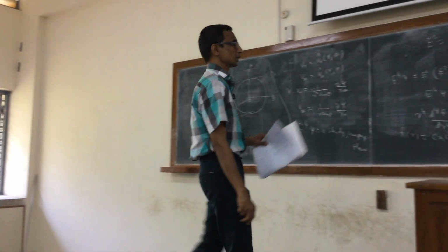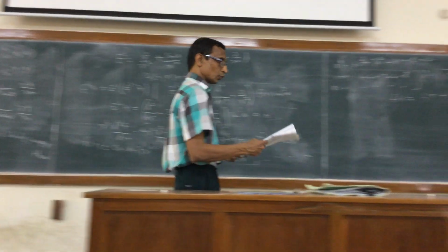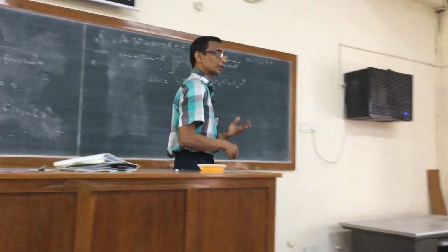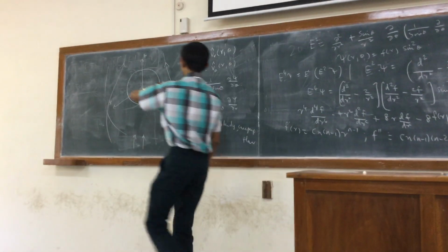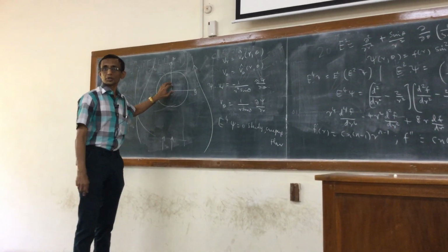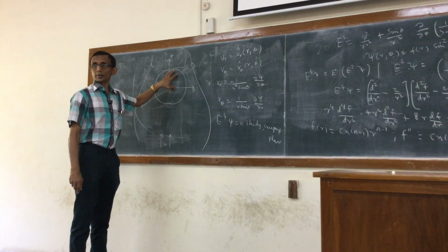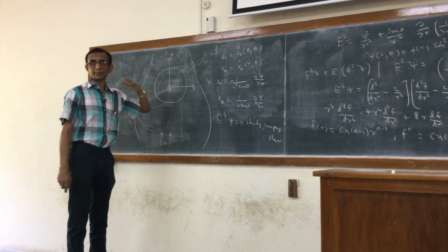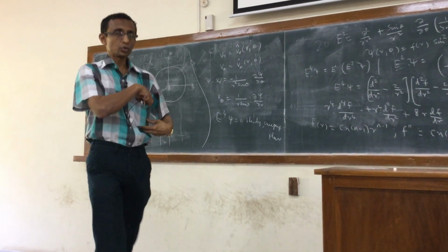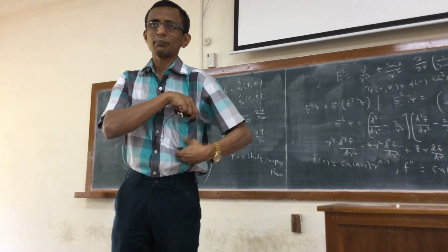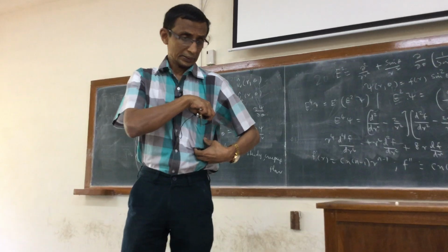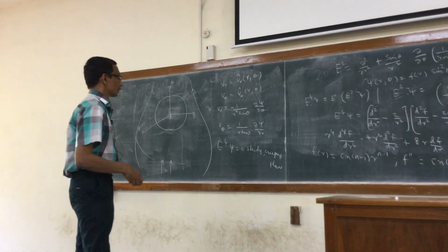So what we have to do is first write down the boundary conditions for viscous fluid flowing past a solid sphere. So two of the boundary conditions would be the no-slip boundary conditions, in the sense that that would give one condition each for V R and V theta, right?